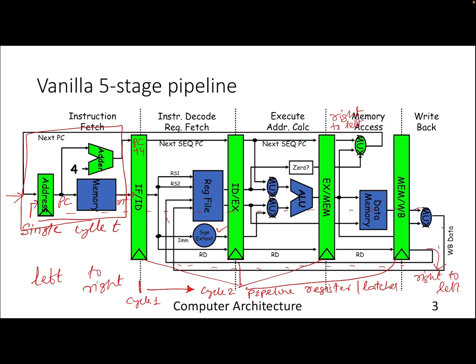So this sequence goes on, and this is cycle 3, where the first instruction eventually performs some ALU operation depending on the source. It can be from the immediate values or from the register data that was actually stored here. So you will find all the register data stored here, okay? And eventually you go to cycle 4 for memory operation, and finally, once you have the data and you want to write back to the register, then you come back and write into the register with the data, right?